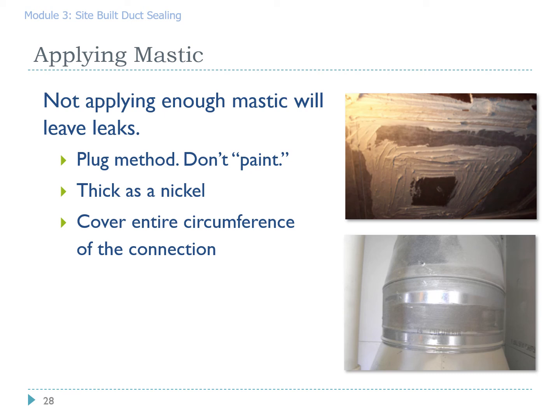I want to draw your attention down here to a duct system that was allegedly sealed. What you can see here is you can actually read the ink stamp through the mastic. That's just too thin to win. The guy was painting, he was definitely not plugging. Don't be afraid to make that mastic good and thick.